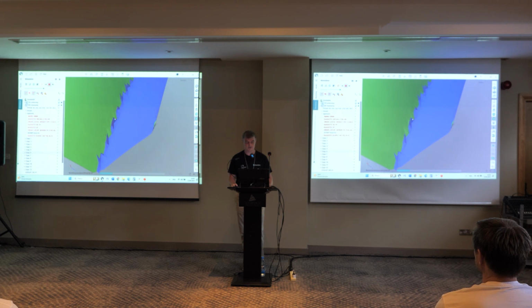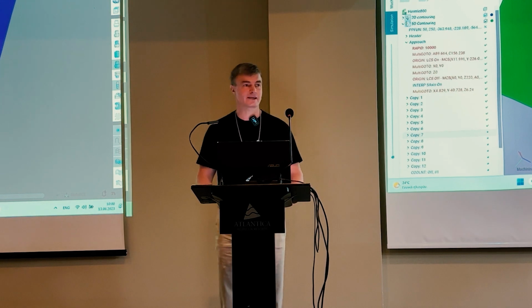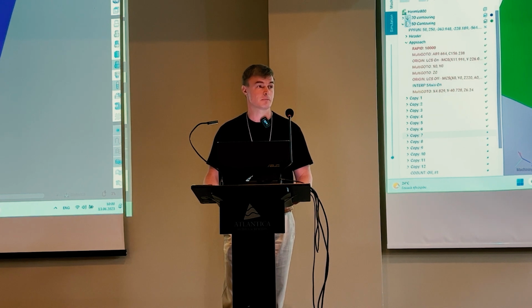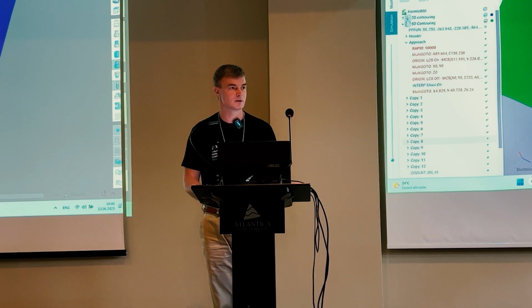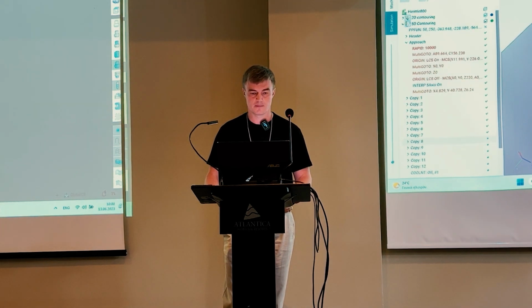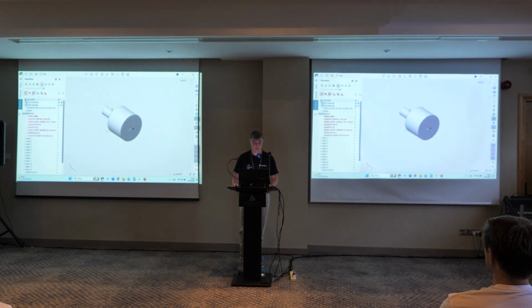And here is the resolution of voxel, and it's for example for the cases when the tool size is much less than the workpiece. For example, wire EDM or laser cutting. For example, we have a huge part and the laser diameter is less than a millimeter, and the size of the voxel can be less than the size of the tool. So this voxel simulation cannot be used. Let me change the simulation mode to solid and resimulate it again.